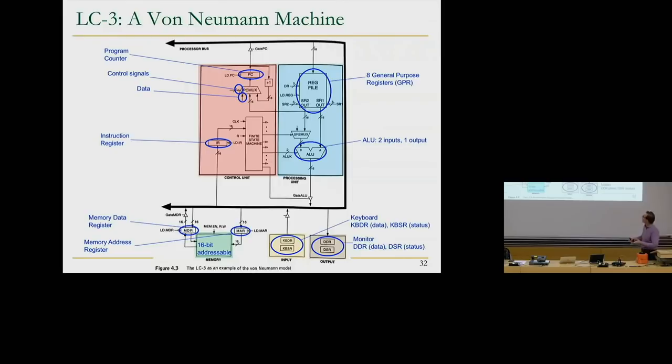But hopefully, this is called a data path, and there's also some control logic. But basically, this shows you the movement of the data. Data meaning some number of bits. So program counter needs to get loaded onto this bus and placed into the memory address register. And then you wait for some time, memory responds, the data appears in memory data register, and you need to make sure that that gets loaded into the instruction register. That's how you fetch an instruction. And we will see the step very clearly.